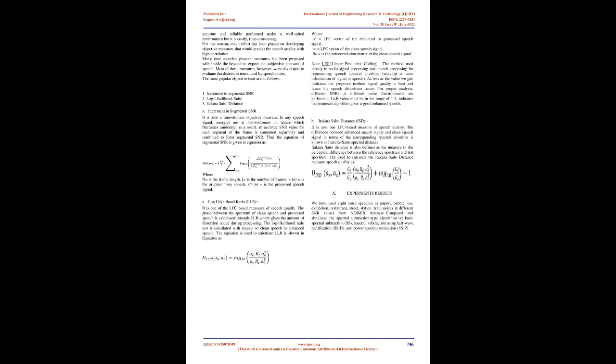MOS is a commonly used measure for audio and audiovisual quality evaluation. MOS, depending on whether the score was obtained from audiovisual, conversational, listening, or talking quality tests. MOS specifies that listeners should be seated in a quiet room with room noise level below 30 dBA with no dominant peaks in the spectrum.